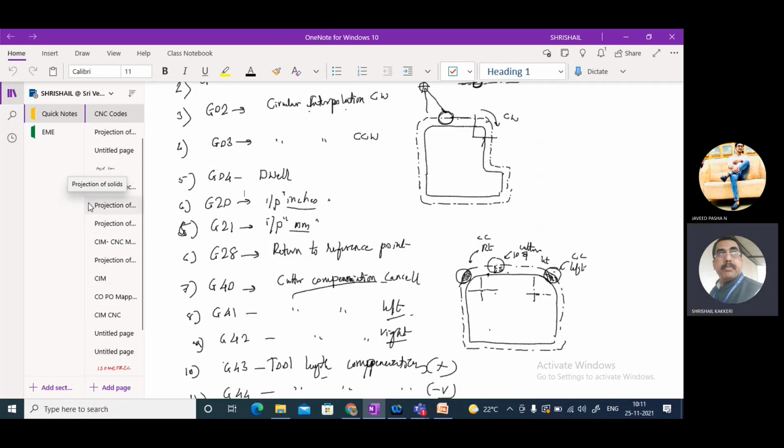Whether the cutter is a multi-point cutting tool or a single point cutting tool. How many of you say it is a single point cutting tool? Here no marks, nothing, just a discussion. What is called a single point cutting tool? A particular point will be engaged in removing the material. It is a single point cutting tool. Almost all the tools we are going to use in the lathe, the turning operation, those will be single point cutting tools. And if there are more than one edge or point engaged in removing the material, those will be multi-point cutting tools.